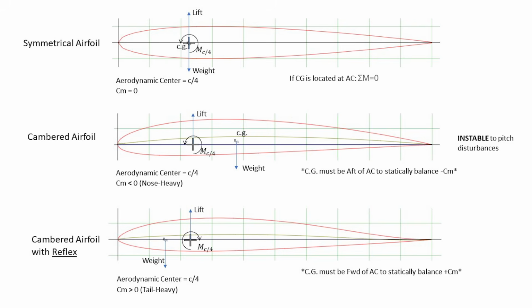And a reflex type wing offers better low speed characteristics than that of a symmetrical airfoil for the same flying wing application. And that's primarily thanks to the positively cambered leading edge. There are two major common approaches to overcoming this instability. And number one is to generate the stabilizing pitching moment in the wing itself.